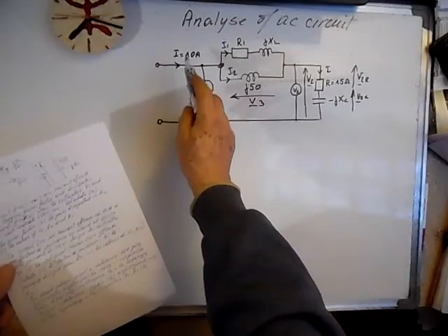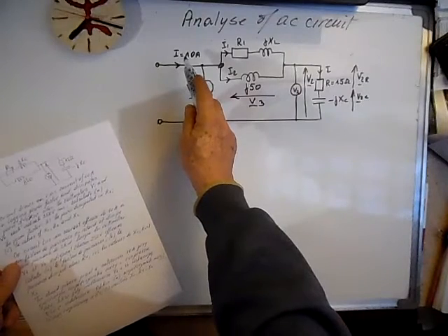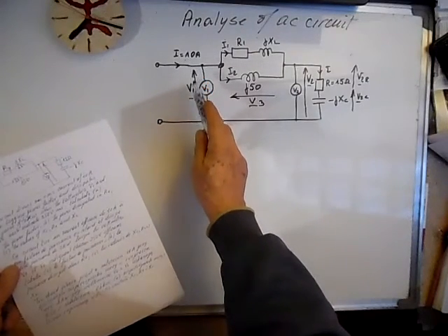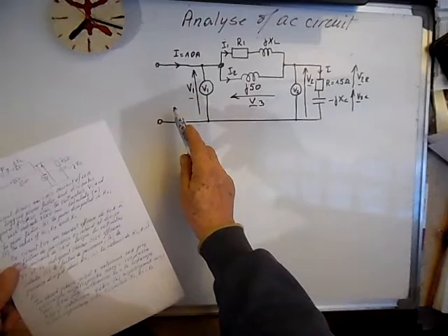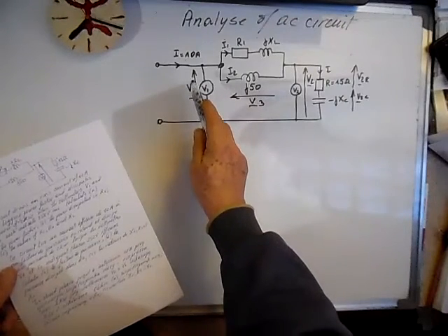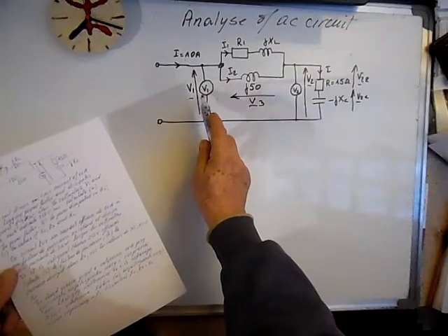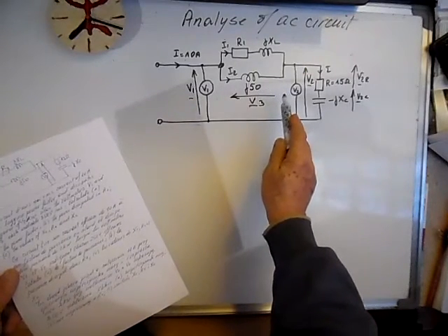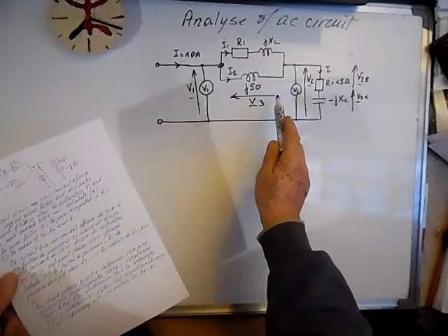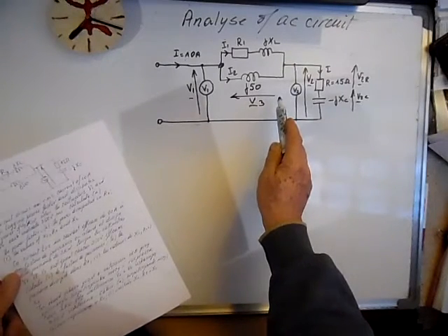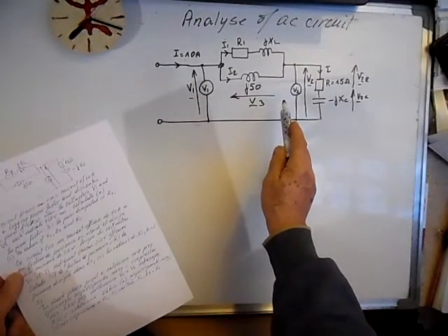This circuit draws an RMS current of 10 amps at a lagging power factor and dissipates a power of 2 kilowatts when the voltmeters V1 and V2 each indicate 250 volts RMS.